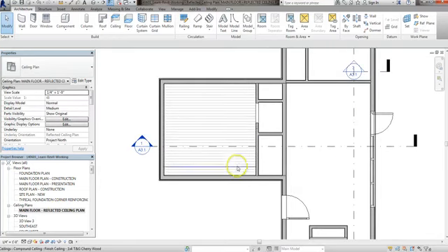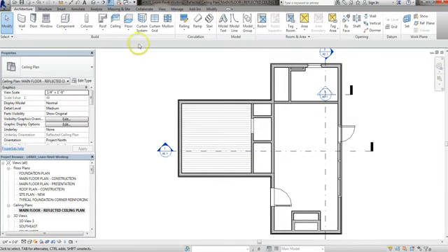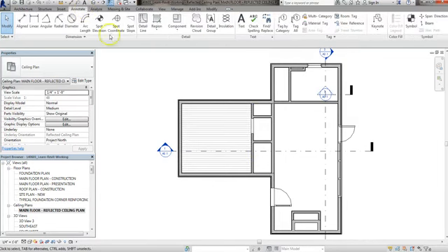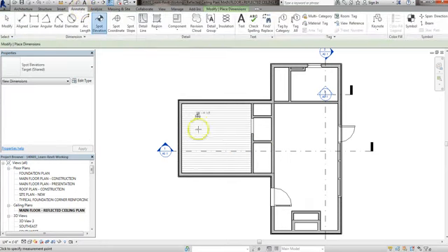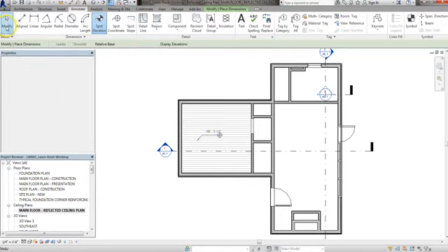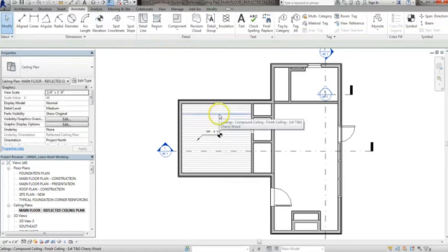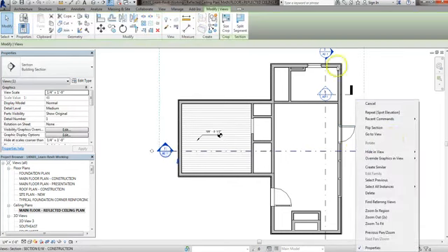And then the other thing that a reflected ceiling plan tells you, besides the type, is the spot elevation, what it's at. So I went to annotate, spot elevation, clicked once, clicked twice, clicked 3 times. This is helpful if you have ceilings of different height, vaulted ceilings, stuff like that. So we just do that. Even in the buildings that just have flat ceilings and no different heights, just to let the contractors and everyone who's building it know that it's at the same height. Other than that, let's go into sections, right?